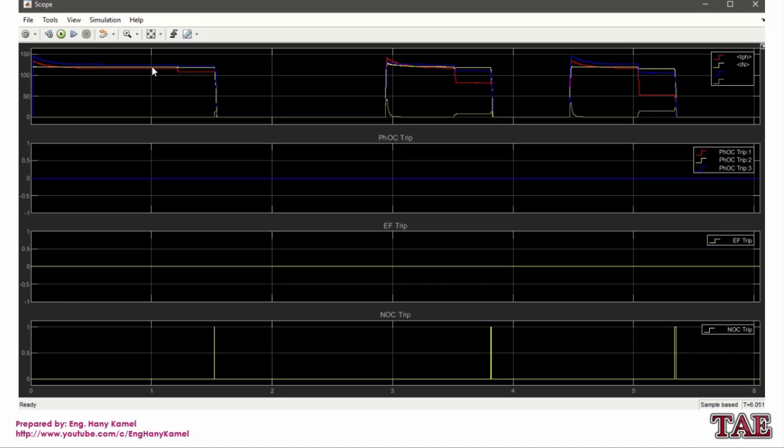This is when the system started, some inrush current for charging current, then the system becomes almost 3-phase the same. Here when we removed one load, one phase, R phase, negative sequence already made the trip, earth fault didn't make a trip, phase overcurrent didn't make a trip.